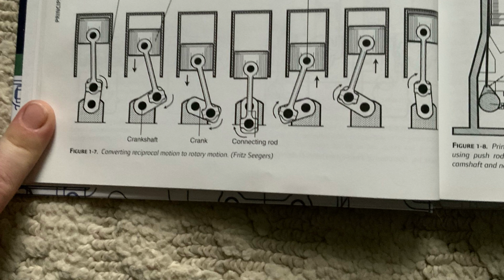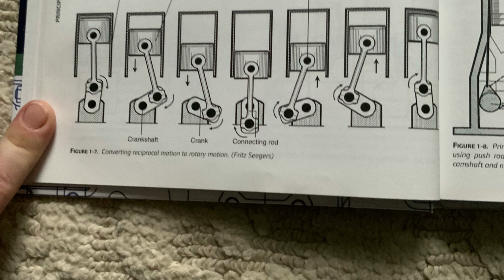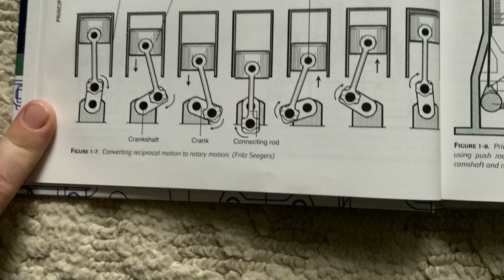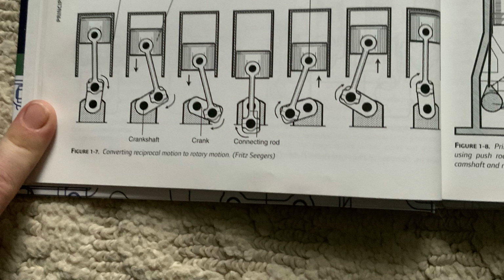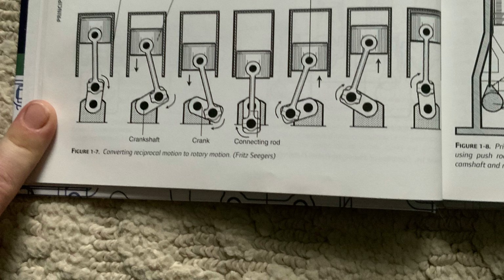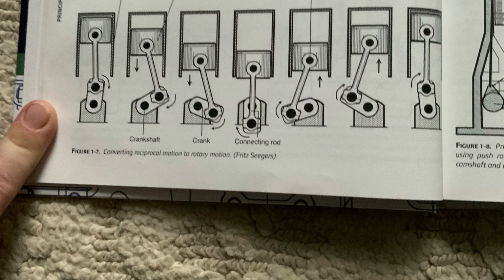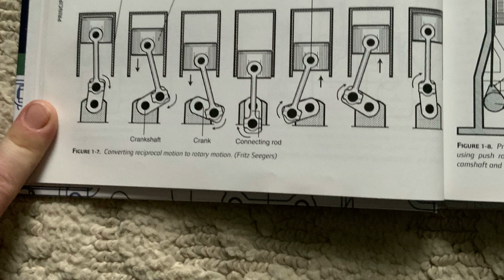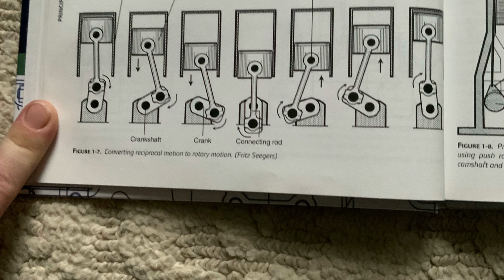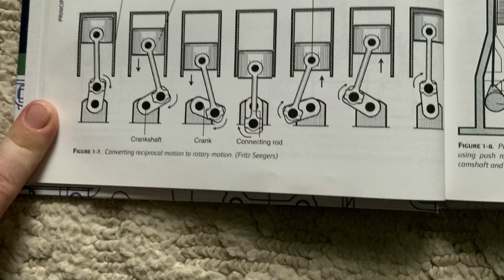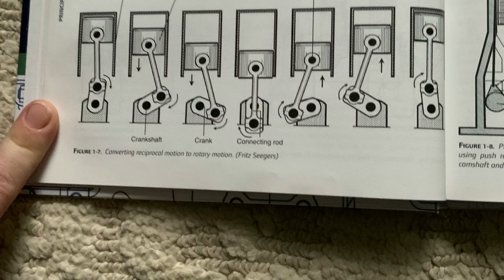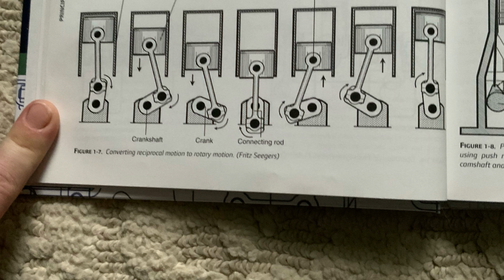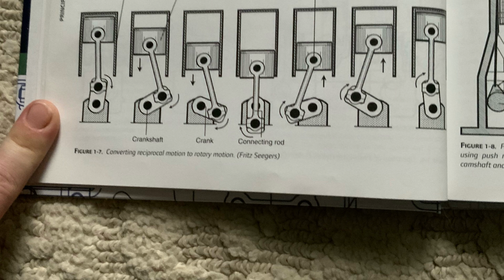A 2-cycle diesel, however, is less thermally efficient than a 4-cycle and has higher fuel consumption, resulting in higher levels of exhaust pollution. The life of a 2-cycle diesel tends to be shorter than that of a 4-cycle model because of the higher loads placed on the engine. What's more, for reasons that will become clear later, 2-cycle diesels tend to be far noisier in operation than 4-cycles, which makes them unsuitable for a wide range of pleasure boat applications. In recent years, tightening emission regulations have pretty much put an end to the manufacture of 2-cycle diesels.